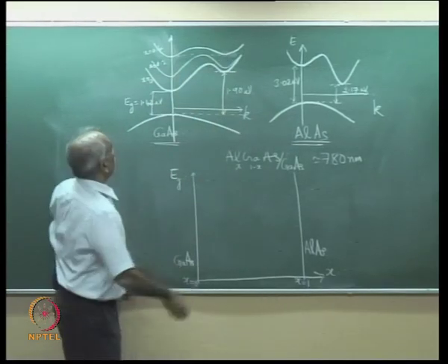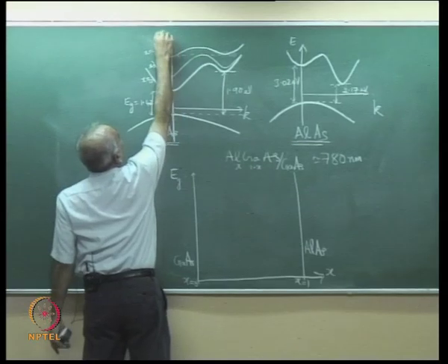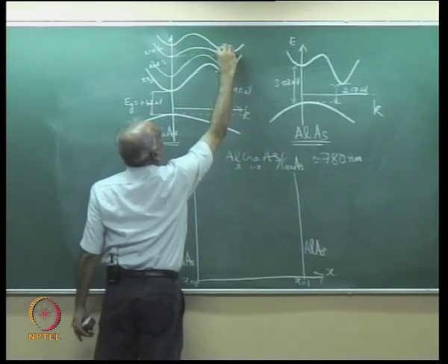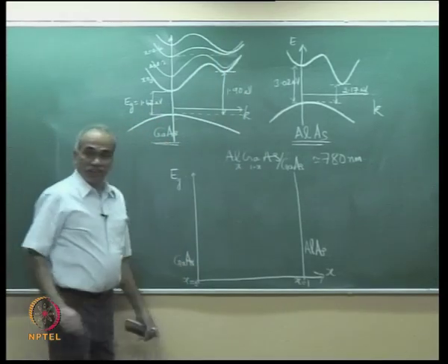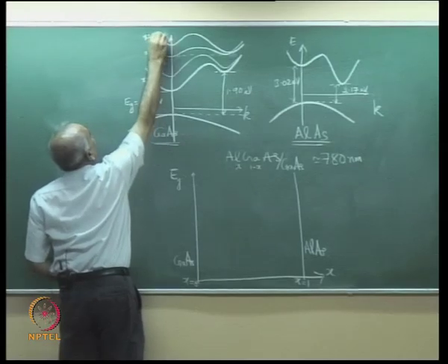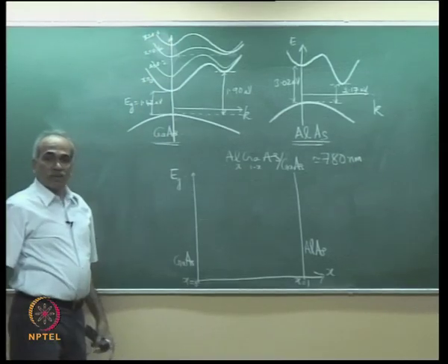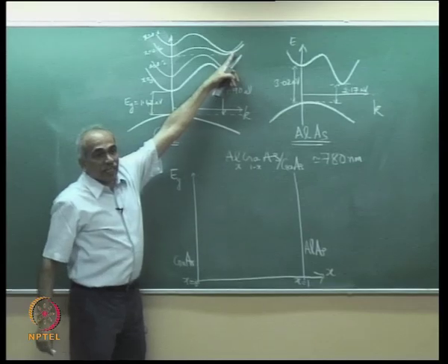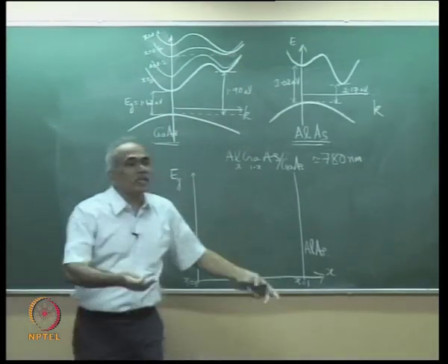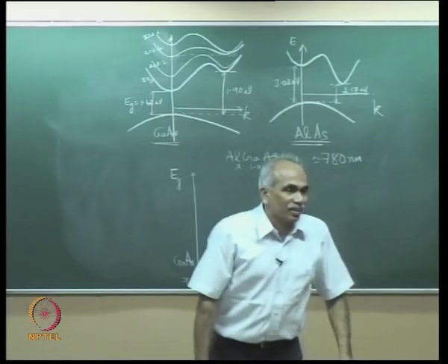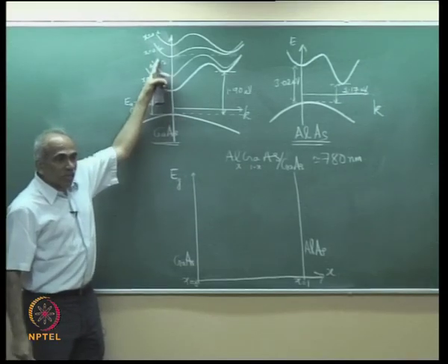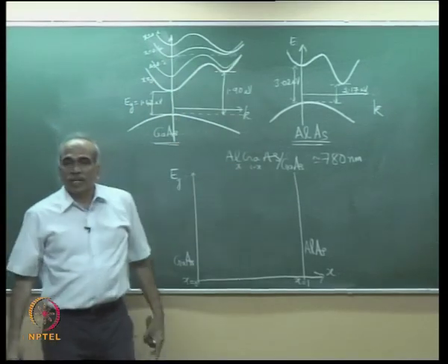After some time, when x is equal to 0.6, this does this. What does that mean? So this is x is equal to 0.6, which means now the indirect gap is smaller compared to the direct gap, and this material has now become an indirect band gap semiconductor. It was a direct band gap semiconductor. As you increased x, it became an indirect band gap semiconductor.